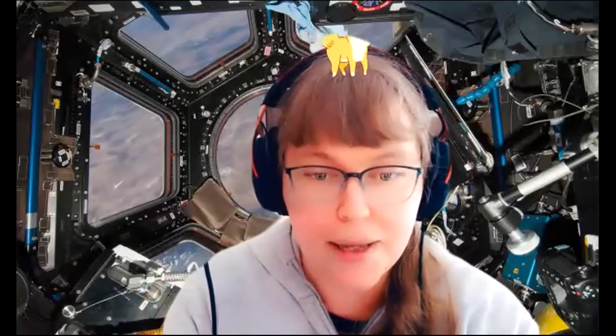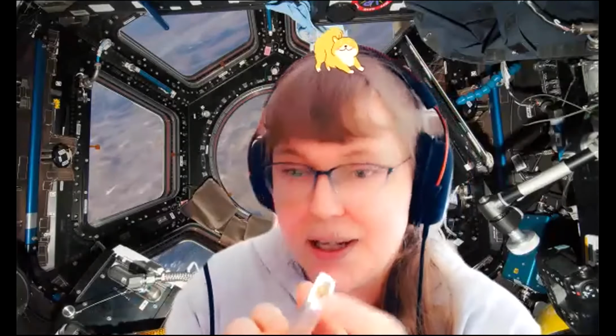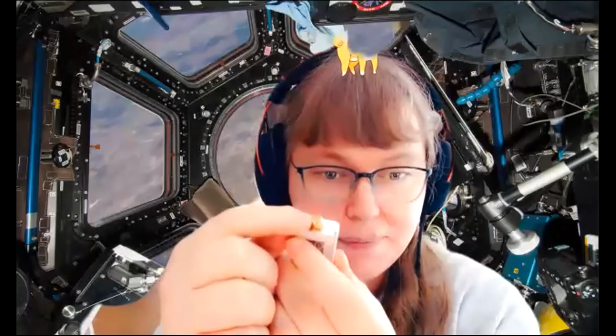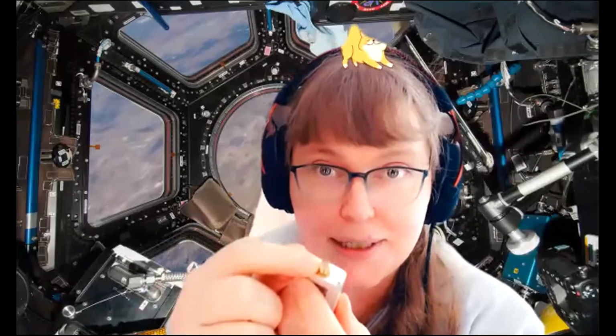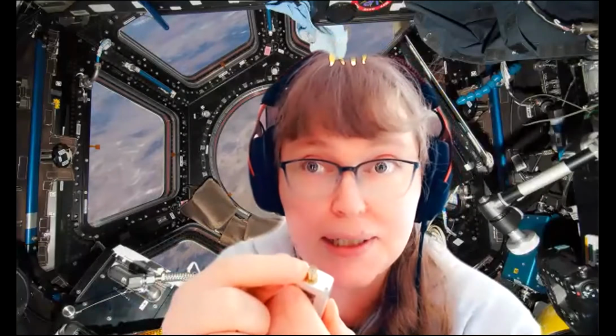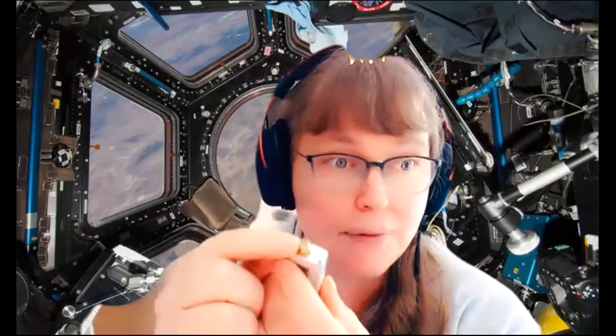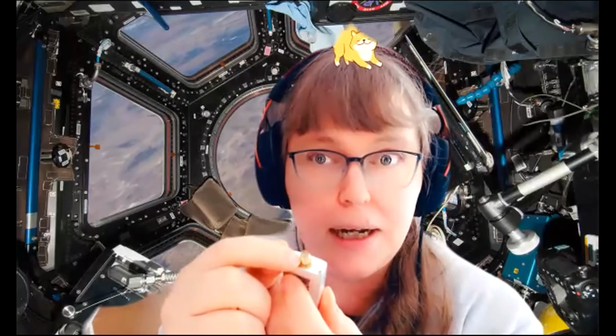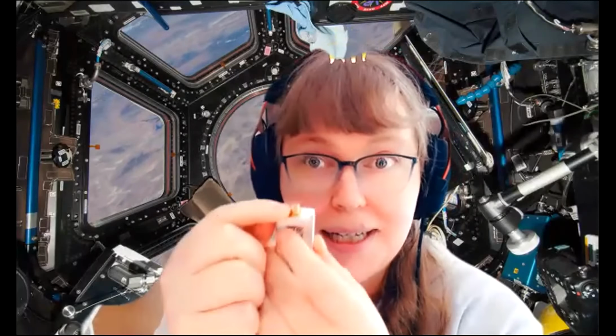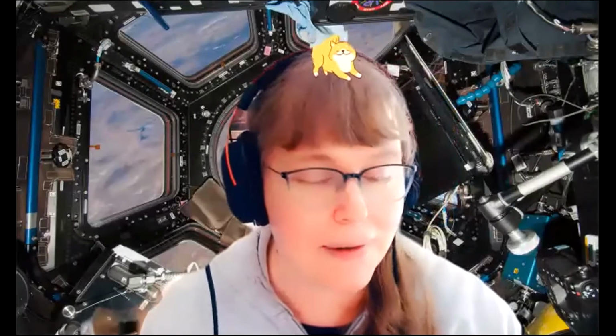Okay. Yeah, and before I go, let me give you a pro tip. If you get into using a lot of SDR stuff, I mentioned the antenna. That's of course very important. But you also want something called a low noise amplifier. And you also want to have a filter. Those are going to help you a lot. Just a pro tip. If you're having issues, amplifier and filter.